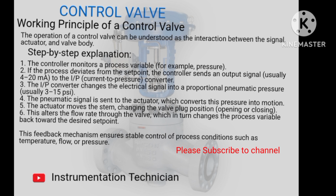The operation of a control valve can be understood as the interaction between the signal, actuator, and valve body. Step-by-step explanation. The controller monitors a process variable, for example, pressure. If the process deviates from the set point, the controller sends an output signal, usually 4 to 20 mA, to the IP (current to pressure) converter. The IP converter changes the electrical signal into a proportional pneumatic pressure, usually 3 to 15 psi.